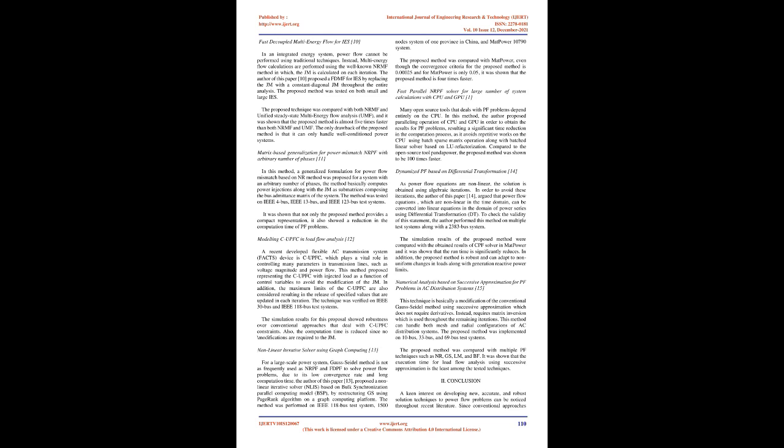The method basically computes power injections along with the Jacobian matrix as submatrices composing the bus admittance matrix of the system. The method was tested on IEEE 4 bus, IEEE 13 bus, and IEEE 123 bus test systems. It was shown that not only does the proposed method provide a compact representation, it also showed a reduction in the computation time of PF problems.